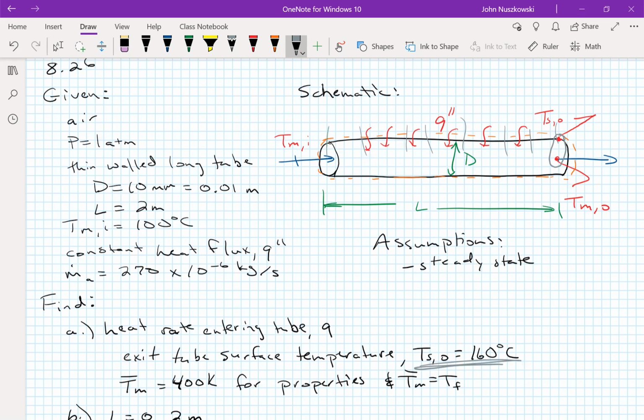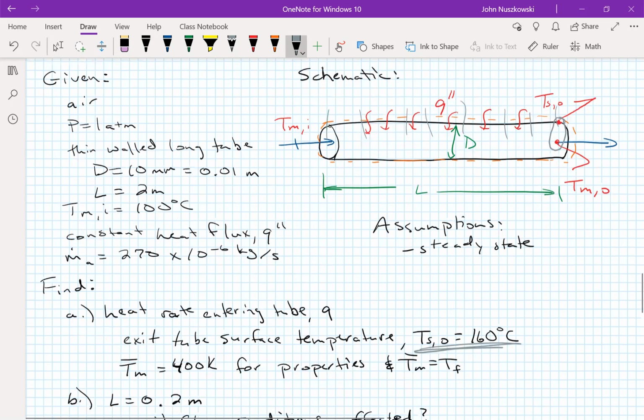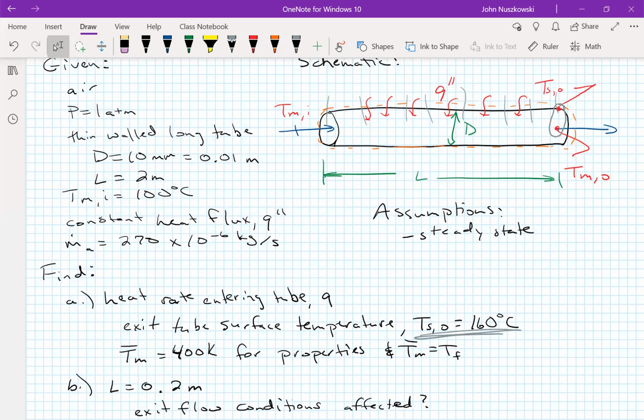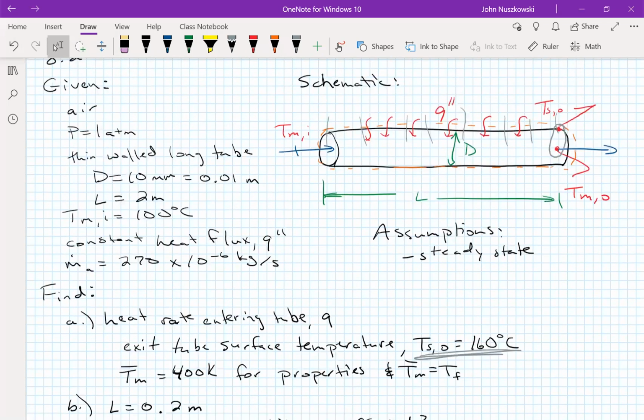They definitely can be different, right? But what equation do we have that relates those two? Newton's law of cooling. Yep. Right at those points is what relates those two points to a heat flux. We have convection. That's what's going on at the outlet to that surface.